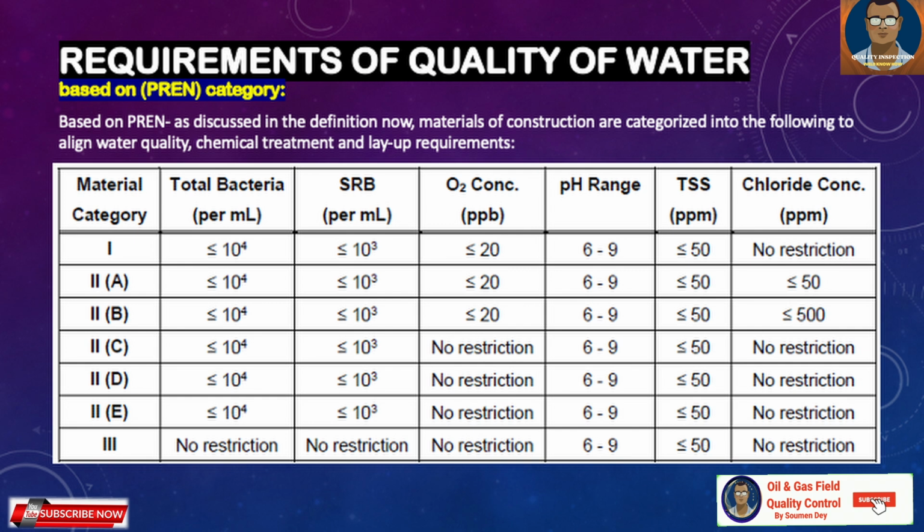Without clean water, the test should not be done, because if the water has a lot of suspended things and is dirty, full of foreign materials, these will get stuck in the system and it will be very difficult to clean later on. So we need a clean system after hydrotest. Water cleanliness, or clear water, is mandatory for all categories.